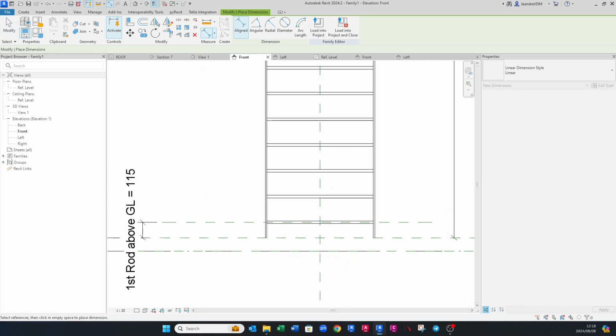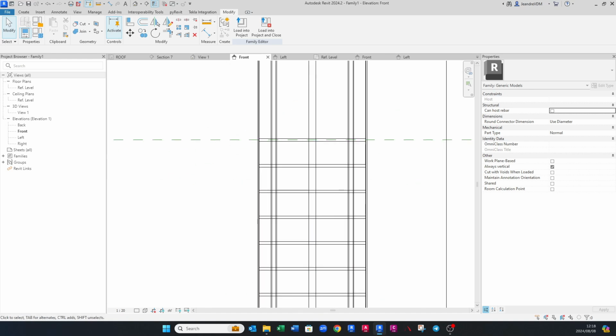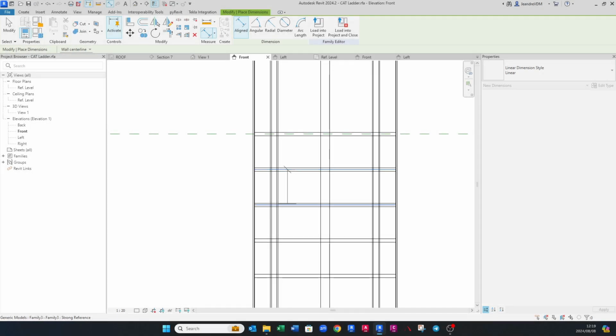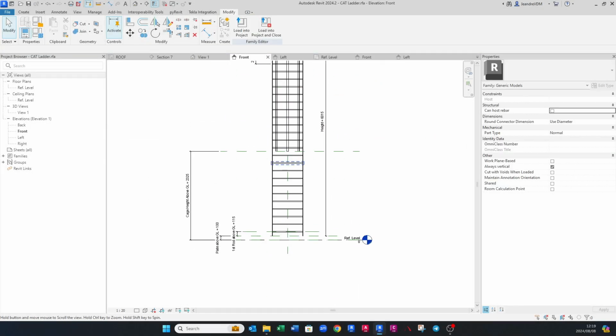Let's see, that's 192. We actually want it spaced at 200 mils. Let's see if we go here and we say round up that. Take out the +1, say apply. Just take out the millimeters, say apply. Still not. Maybe it's because we don't have the brackets in. Like that. There we go. Let's just see the dimension now. There we go. That's the 200 that we want.